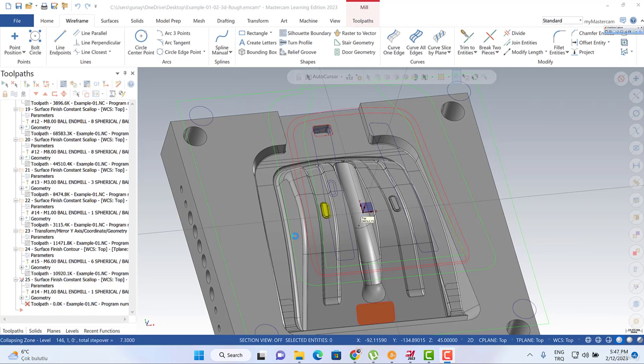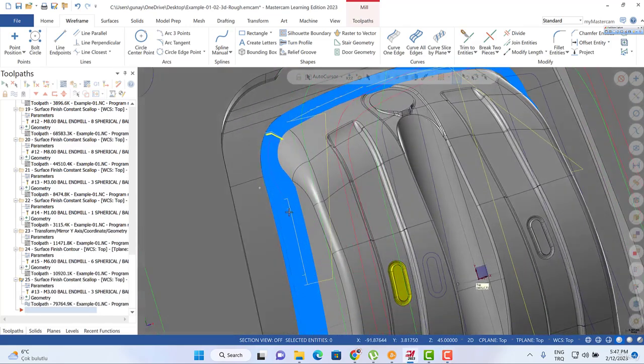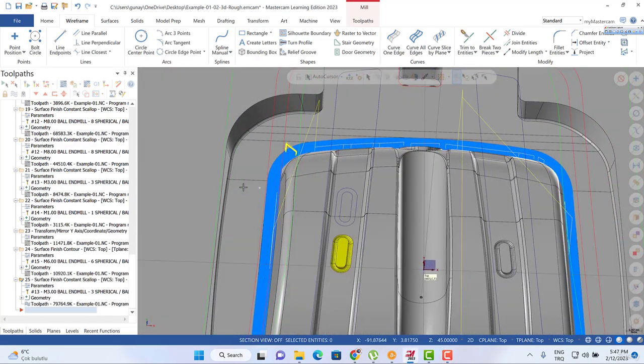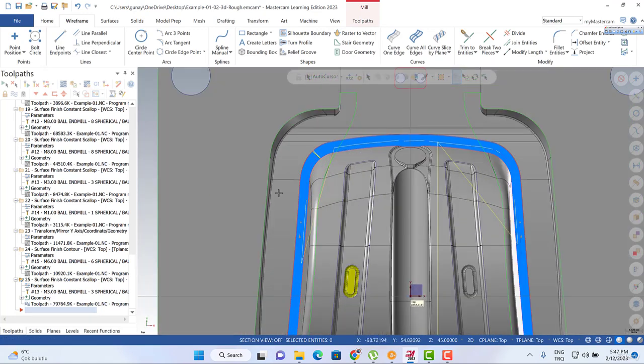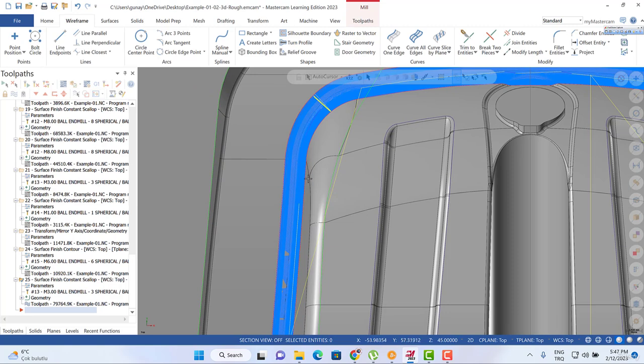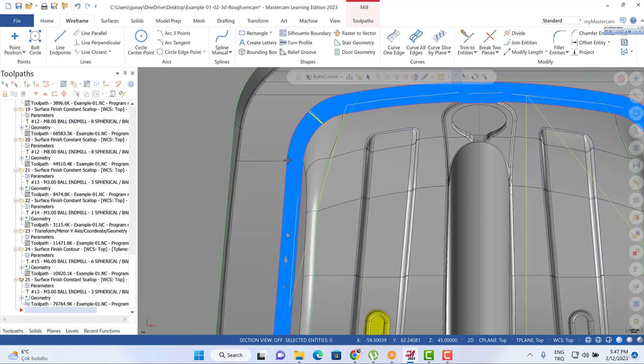Anyway, okay, let's see what we get. And oops, we are using the 1mm tool here. Maybe before that we should use the 3mm ball toolpath here. Yeah, that's calculated right now. You're gonna see that according to that perspective, when we consider here, let me focus on the top view. You're gonna see that kind of perspective here.